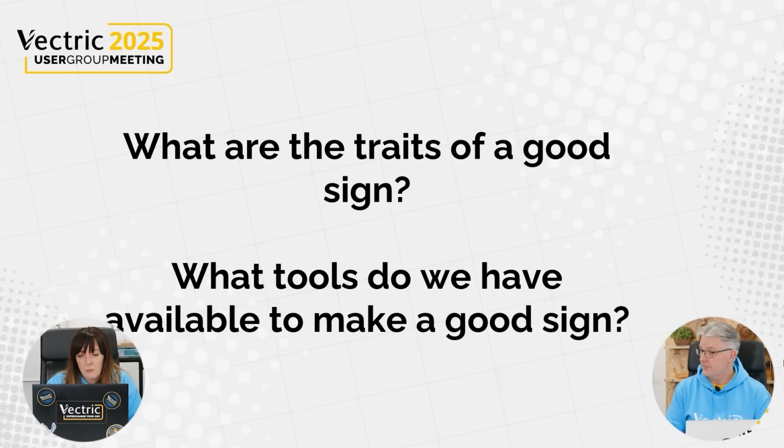This is one of the favorite things I do all the time. To copy something across your job or up and down across your job, it's really easy to do. If you hold down your Control key, that means copy. Shift means across one of the vertices. And I'm going to go H, which is horizontally, and there I have a copy now that's directly across from my other star in the same position, assuming I've centered everything else along the way.